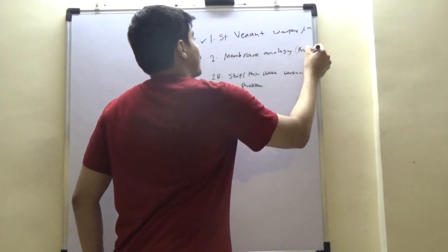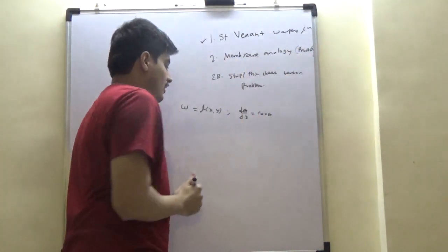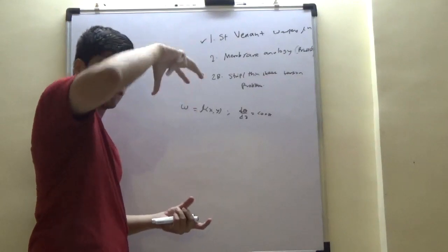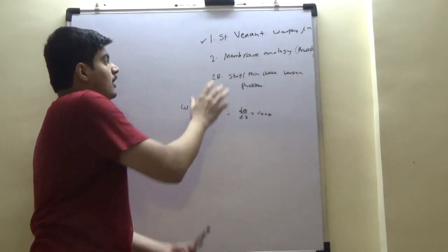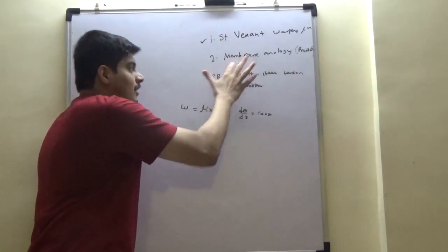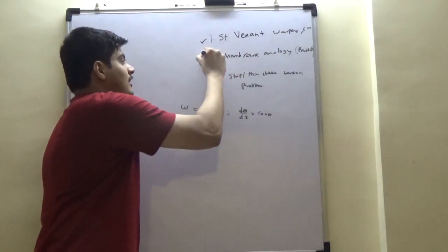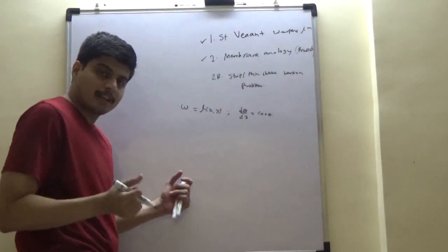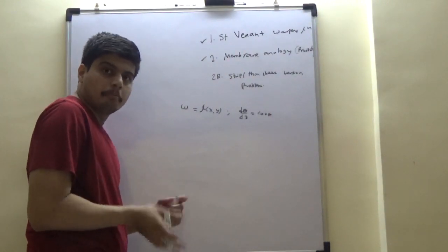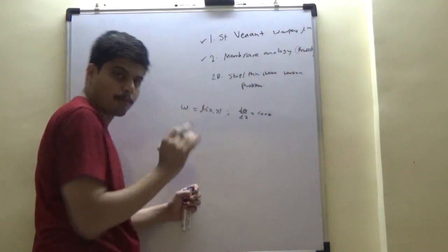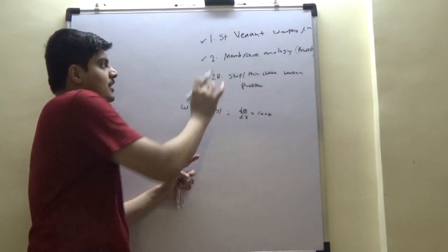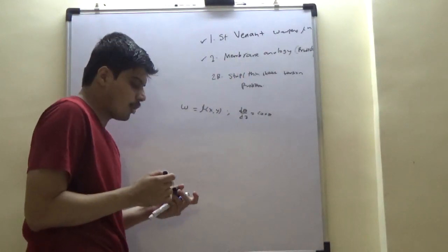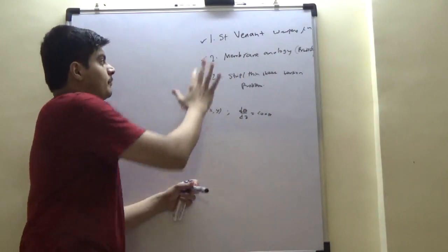It is his analogy that if you look at a membrane which is squeezed and which warps out, twists to resist that load, the problem of torsion and membrane are mathematically equivalent. The phenomena governing is slightly different, but the setup of the problem is such that the analogies are identical, and it simplifies your task to solve these equations in much detail.